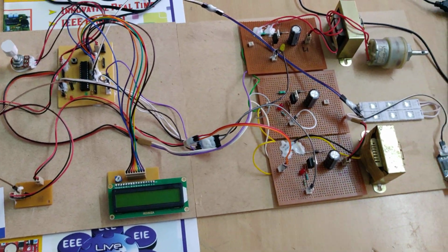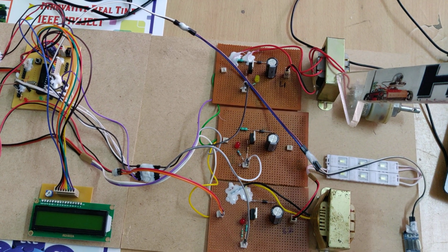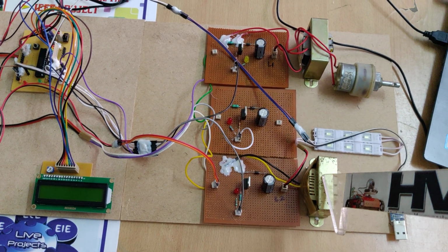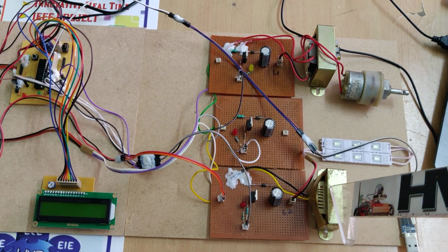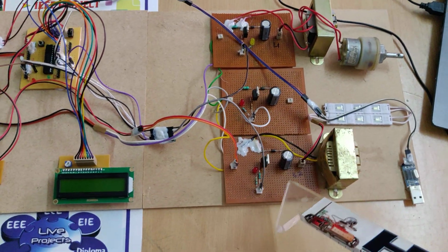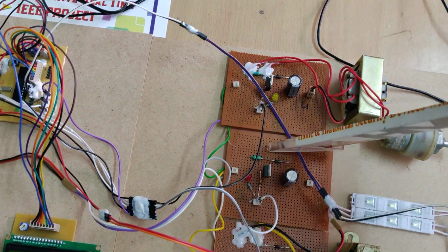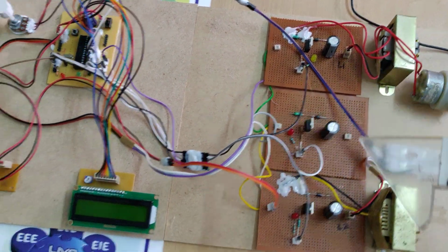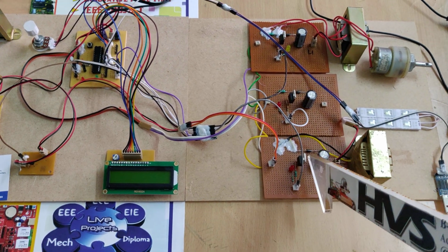Okay, so let us see the demonstration. Here these 2 transformers are used as inductors, because the primary and secondary coils of the transformer are made of copper coil, so we are making use of them as inductors in our buck and buck boost converters. Also, in the boost converter there is one inductor here, we can see that it is 100 microhenry, and here the 3 MOSFETs are IRFZ44.